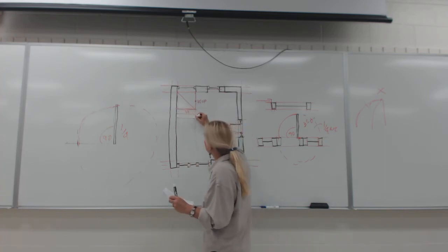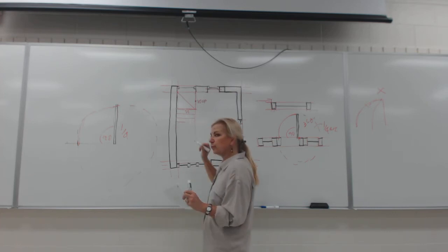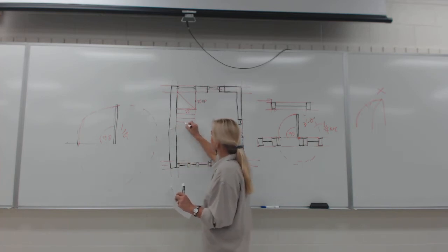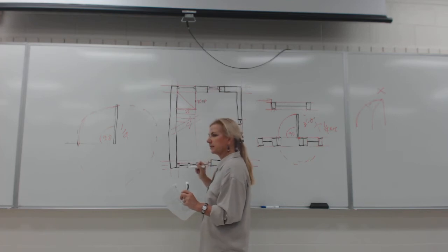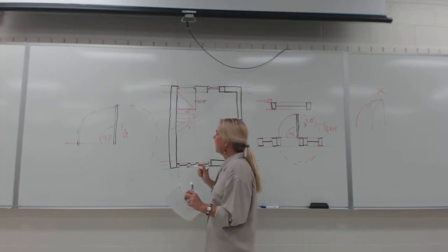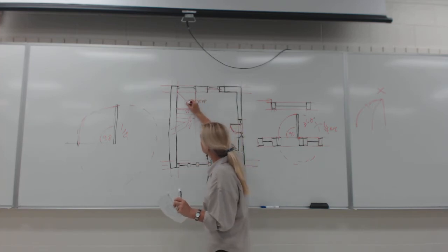1, 2. But before you get too far, ladies and gentlemen, we need to cut. We talked last week about the cut line. We're going to draw 2 lines like this with a freehand squiggly line like this, and not show anything here. And that's the cut line because we're going to show stairs going up here with an arrow.